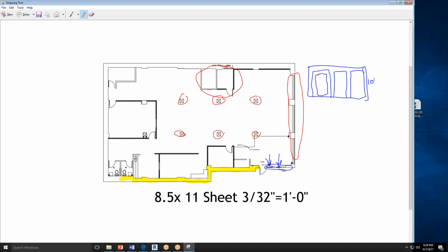So draw only the core, ignoring all the interior. So it'd be this whole guy and the bump-in, all the bump-ins, even this little notch guy, this whole corner around. And then there's this weird thing, and my Revit people, because I'm making them learn how to do crazy walls, but I don't care if you cut it at this first bump and then one across. You don't have to draw every notch, but you can if you want to. And then we'll build the wall out to there. But it's all just wall.